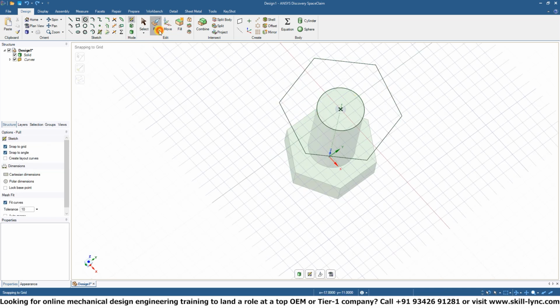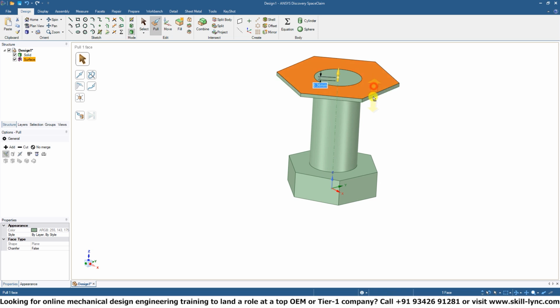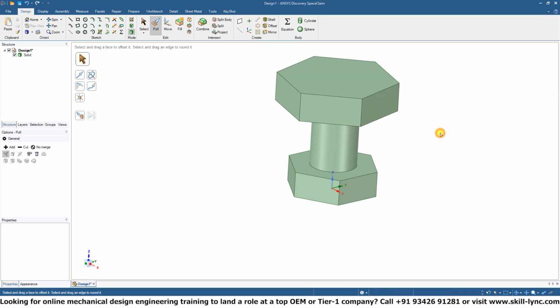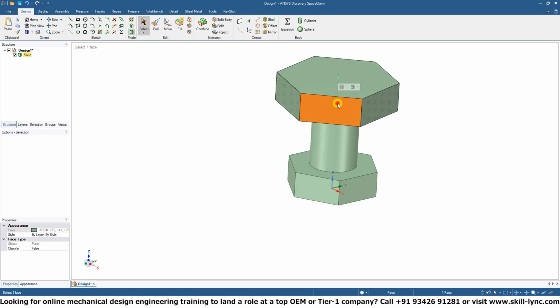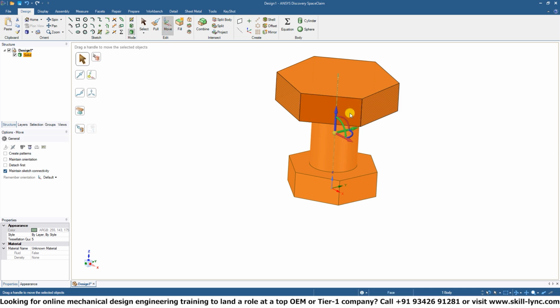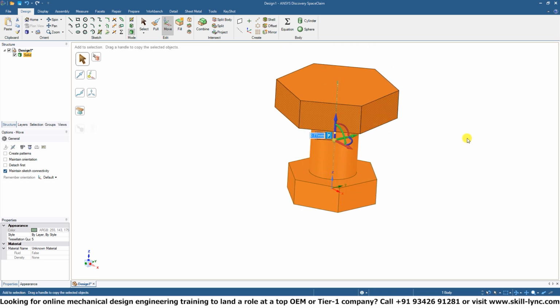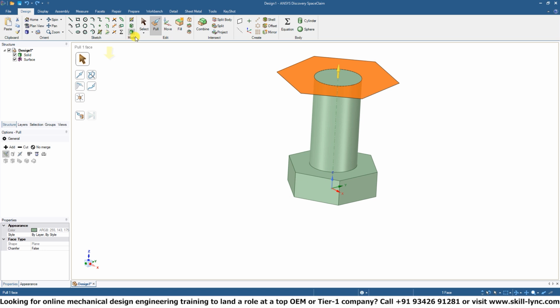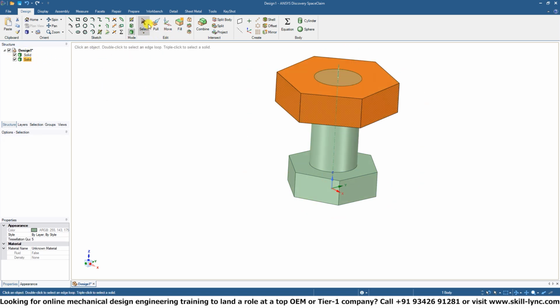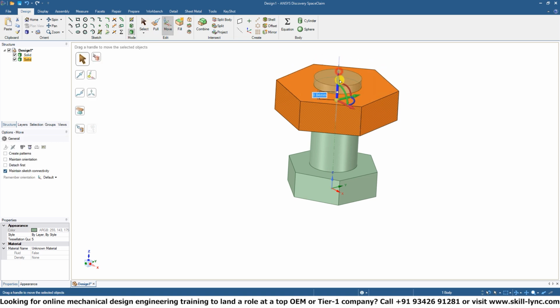If we didn't do that, as an example, let's extrude it again without using the no merge tool. Now, if I clicked on and selected this body, it would select the whole body. So we wouldn't be able, if we use the move tool, to move that nut specifically because it's one whole solid body. By using the no merge, you can create an assembly of parts, several different bodies, and that gives you some more options when you're modeling or creating geometry.